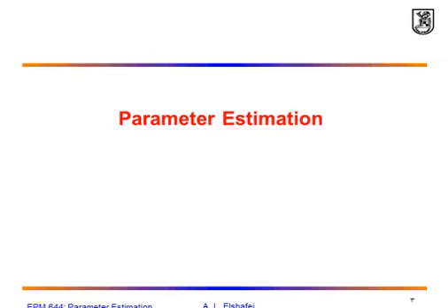So let's start our first topic on parameter estimation. The final objective is to have a recursive technique to calculate the system or the controller parameters, and that will be online and in real time. The basic algorithm is based on the least squares principles. However, to give an overview and a comprehensive understanding of the problem, we'll start by talking about the system identification problem as a big problem, and then go down to the parameter estimation part.